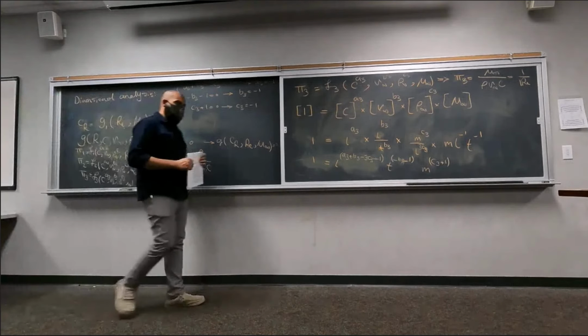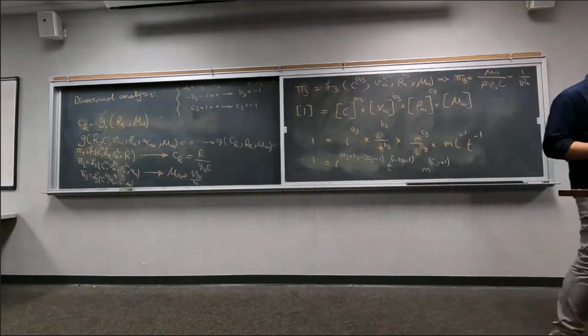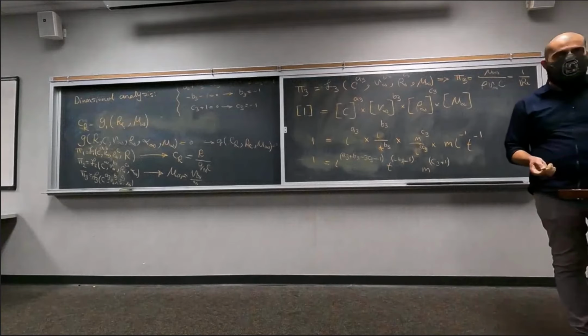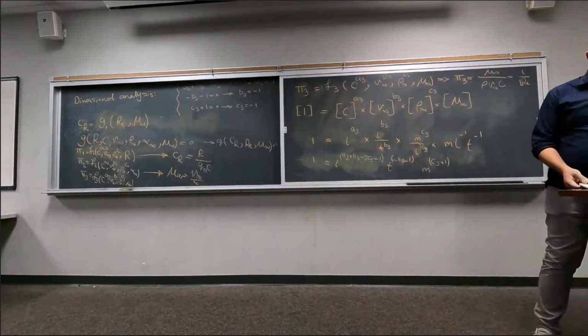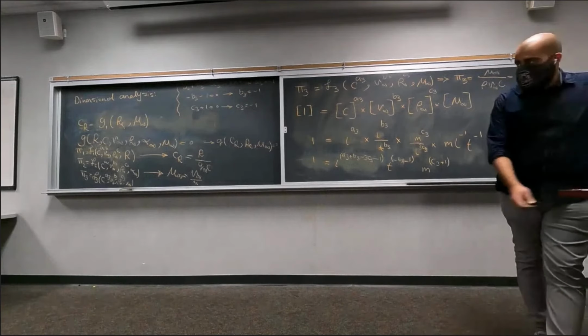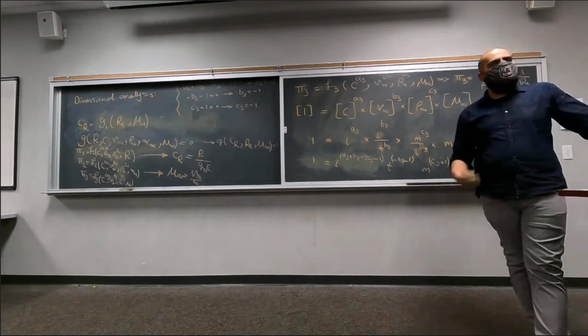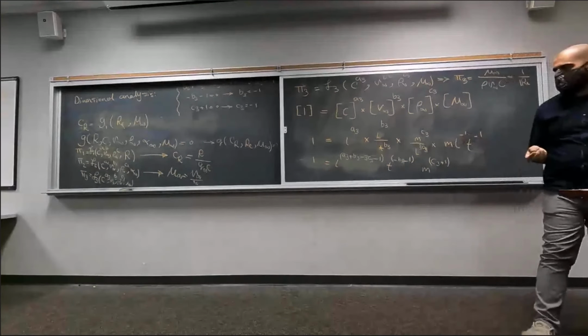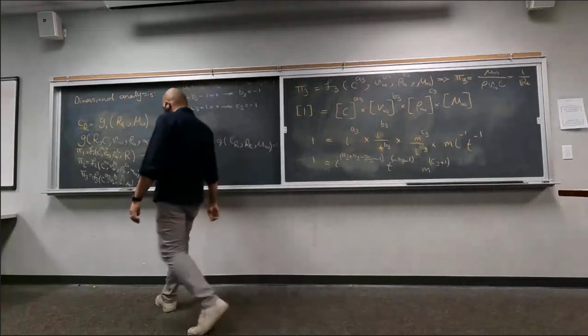This is the Buckingham Pi theorem that is going to help you do the dimensional analysis and reduce the number of variables in your system, right? Reduce the complexity of the system when it comes to the analysis. This type of analysis actually has another consequence, which is essentially the idea of flow similarity.